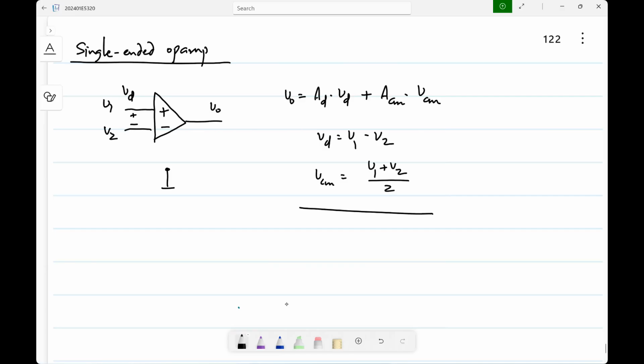Now, what is preferred on integrated circuits are fully differential structures. That is, for every signal, you use a pair of wires, right? The two voltages, for instance, on the wires will be equal and opposite. That is what is fully differential signaling. Why do we use this? What is the point of this fully differential stuff? You have encountered fully differential before in analog circuits? What are you aware of? So why do we use it?